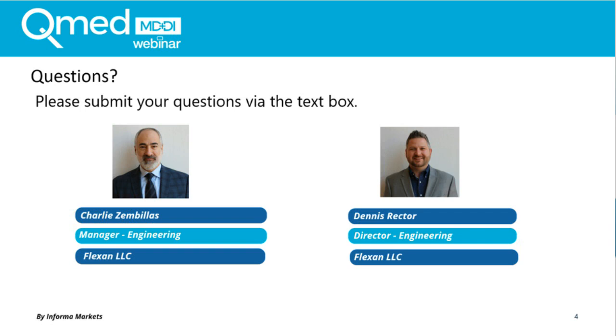If that's the case, I don't see the surface finish changing as the balloon expands. I've used ribbed extrusions for catheter balloons before. When the balloon expands, it's the same smooth surface finish, just like when it's extruded. And they generally recover very well. You can expand them and deflate them over and over again. We don't have any measured studies that would show a difference there. Correct. All right, thank you, gentlemen.